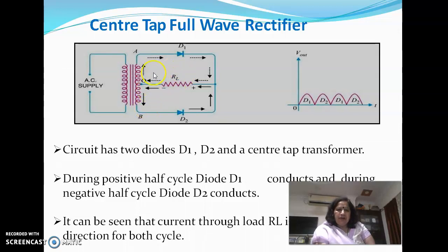So again, the complete voltage across the upper and lower half of the secondary winding will appear across the diode D1, that is twice the peak inverse voltage or twice Vm, we can say. Okay, twice Vm. And the current conduction will start taking place from the terminal point B through the diode D2 and indicated by an arrow through the load resistance RL.